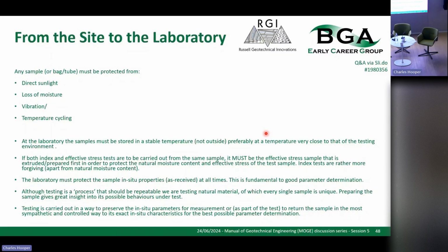It will heat one side of the tube and not the other. Therefore, you will get swelling in one side of the sample and not the other, and it will be changing its fabric inside the tube. Especially overseas in very hot countries, it really does change it badly. But even in the UK, and obviously with climate change, we have to be very careful.